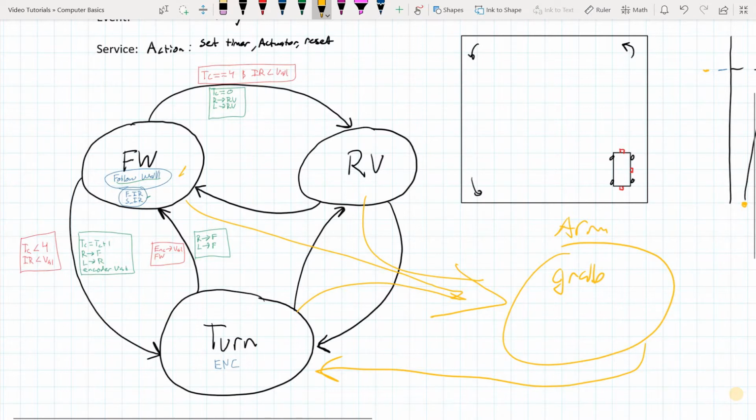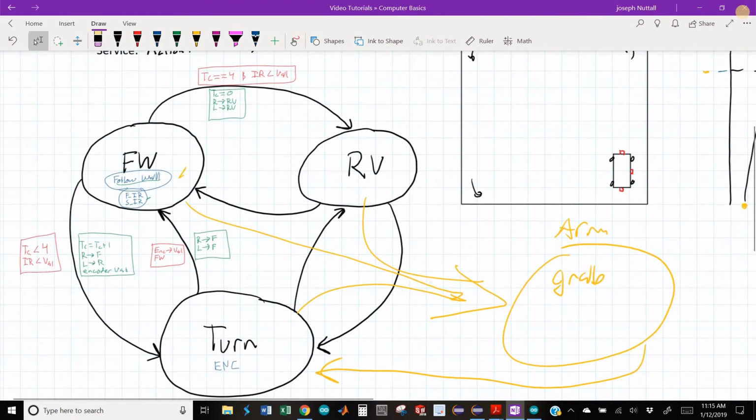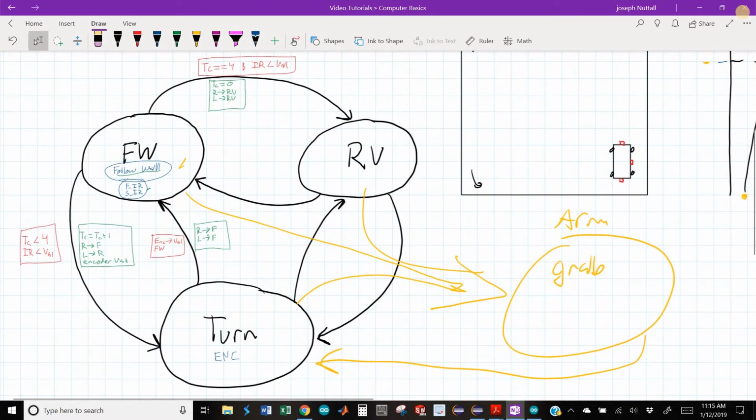I could be running concurrently 8 different states, right? I'm sensing a package over here. I'm rotating at the same time. I'm also computing some value to print something to the screen. So like formatting some sort of user interface screen or whatever, right? I could be doing all of these things concurrently. That's the great benefit of having states. And state transition diagrams can really help to pictorially look at what you're doing and decide how you're going to pull it off.